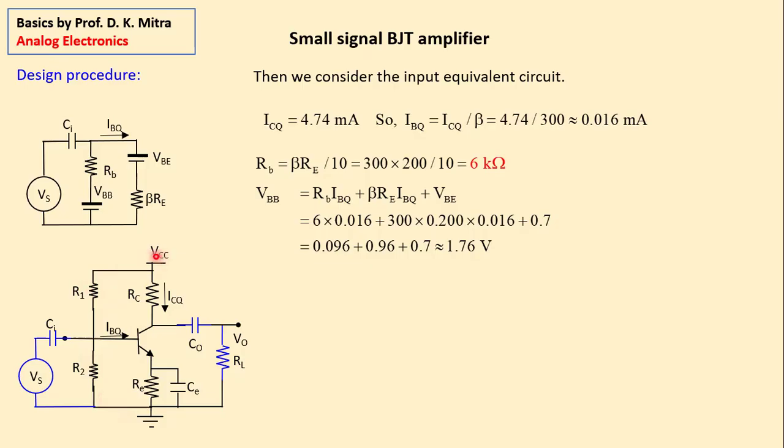So in this line, if it is 10 volt and the resistance is 10K, then the current flowing through this line is 1 milliampere. I would say you still make it lower. Both of these together, you make maybe 12 kilo ohm or 15 kilo ohm, something like this. These are practical design considerations.